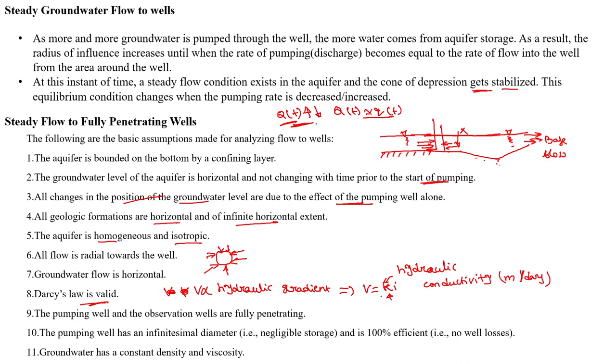So we use well testing or some different methods to estimate this K. We will solve a similar example where our interest is to calculate the hydraulic conductivity using other given data. The pumping well and observation well are fully penetrating, as I told you. In practice we often won't have the hydraulic conductivity value, so to estimate it we use the pumping well as well as observation wells, and we continuously monitor the drawdown.